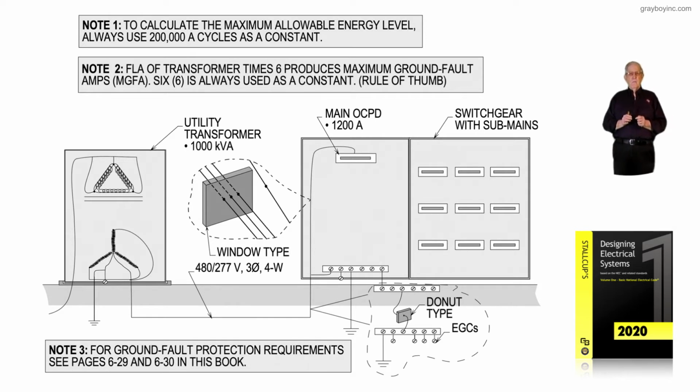So we called the manufacturer and talked to him about it, as we were new to this new rule in the 75 code under 230.95. And he said, well, just take 10% of your device and start there. So if it was 2,000 amp, we take 10% of that and set the relay at 200 amps.